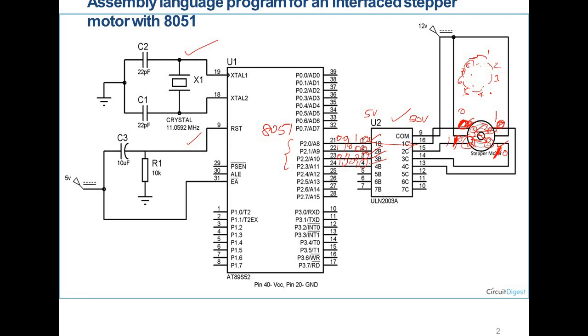If you put it in a loop, then it will be an indefinite rotation. Or if we have any number of specific steps, then we can have a counter, and the steps can be rotated 10 steps, 20 steps, 1000 steps, 100 steps, anything. So that stepwise rotation can be used in any embedded system, so that the mechanical operation can be done, whichever it is. Many examples are there.